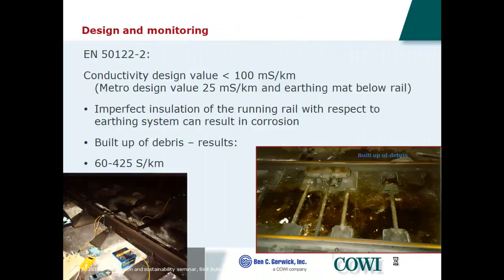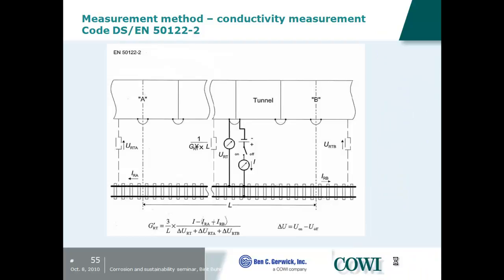Sorry, what are those links? I didn't understand. Which ones? These? No, the links that you show between the segments. These? Yes. They're continuity straps, so that you have electrical continuity between all of the steel, and you can choose whether you have that. Forcing continuity means that if there's a stray current, it goes around and goes over a larger area. Yeah, that would mean that the stray currents could run a longer distance. If you had them isolated, it would also limit the problem to some extent.